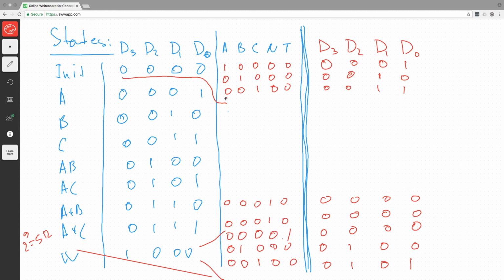So if in state init we receive a timeout, all our triggers become don't care. Okay. So this will help you to actually draw information on the Karnaugh map if you decide to implement the 9-variable Karnaugh map. If you don't want to do this, just forget about don't cares and concentrate only on those rows that you in fact need.